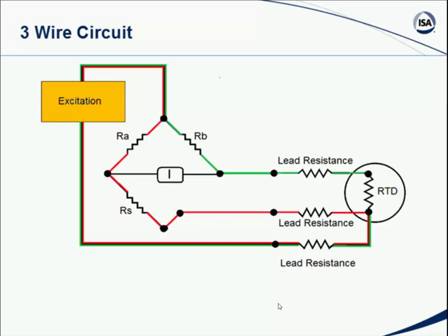or the other of the RTD and bring that back and use that additional wire, whose length should roughly be the same length as the other two leads that are actually being used to make a measurement of the RTD's resistance. We can make a measurement of that lead, and then whatever that measurement in ohms is, we double it, and that's the correction factor we have to add to the RTD's resistance measurement, or subtract from, shall we say, because that would correct for the ingoing and return leads of the RTD itself.